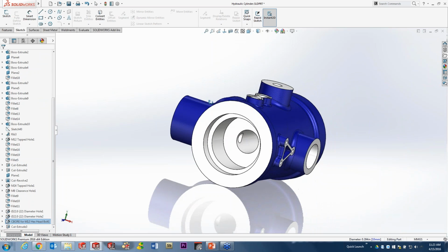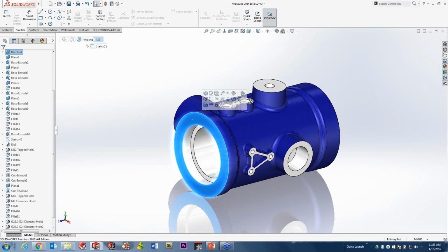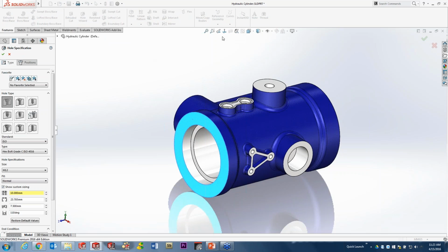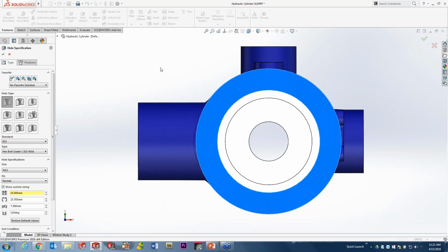On the end of the part, we're going to finish this piece here by utilizing the hole wizard, but that's not generally the feature I'm talking about. I'm actually going to refer to a feature we put in SolidWorks 2015 called the segment tool. Now I'm going to use the hole wizard to illustrate this. When you're dealing with a hole, this is a really great use for this tool, so it's great overlap.